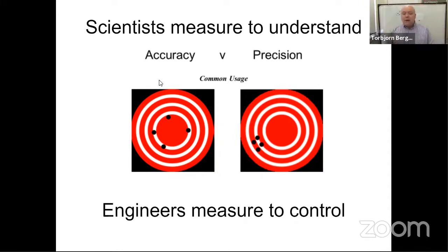So if I'm trying to measure a dimension and my measurement device is not accurate, typically, if we have that kind of a problem, like the picture shows here, it is because we lack resolution in our measurement device. So it's not capable of measuring a number as fine as the number that we want.